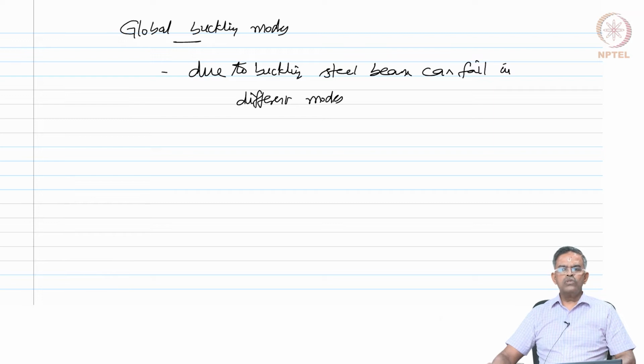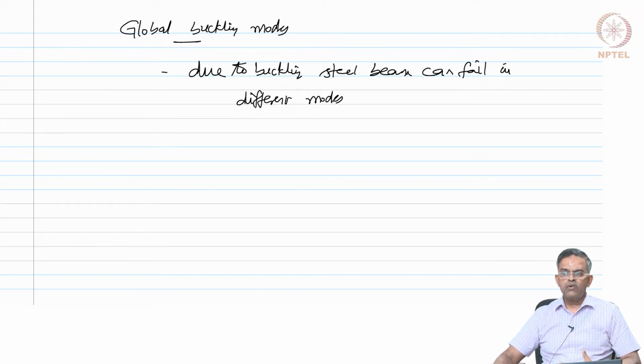The failure modes are governed by type of the load and deformation shape of the member. Furthermore, they can be subject to different types of deformation simultaneously: bending, torsion and warping. The resistance of the beam depends on its stiffness in different modes of the deformations.